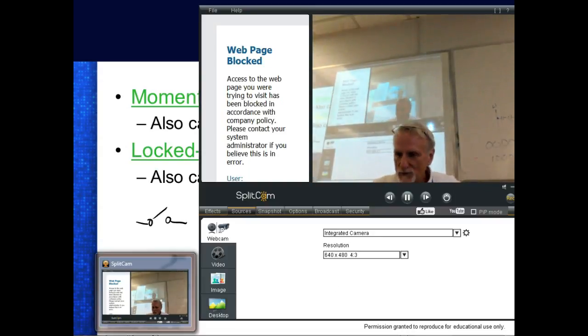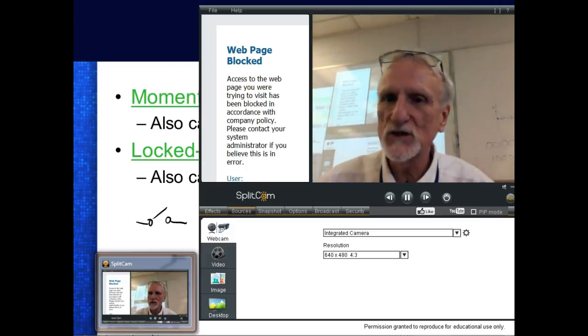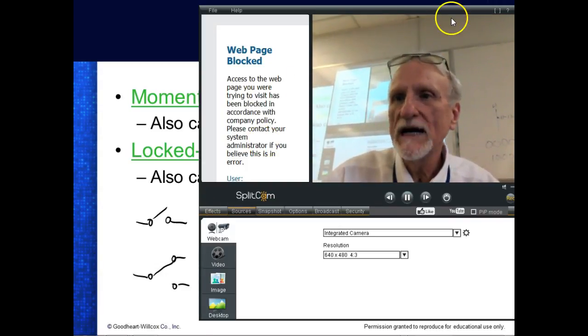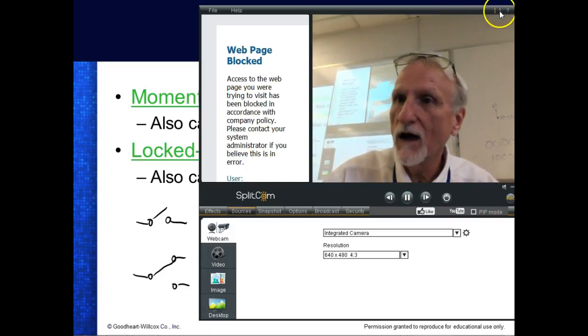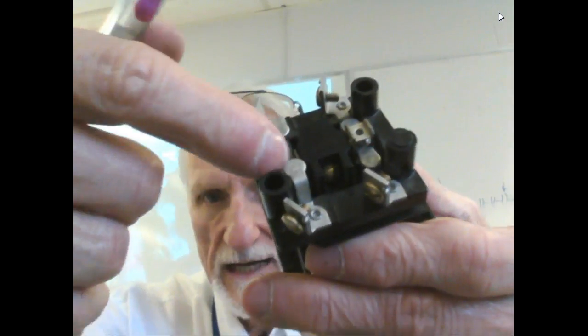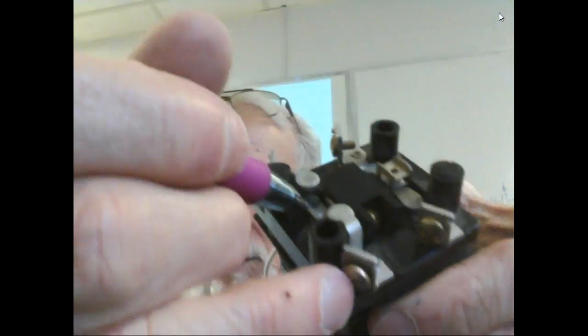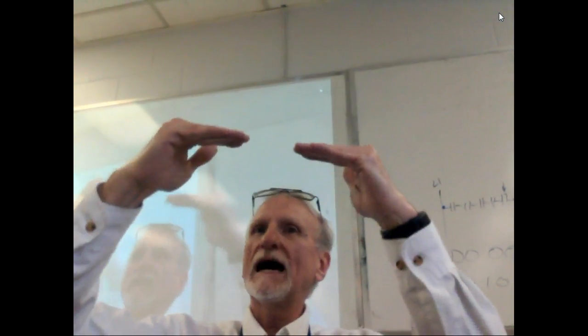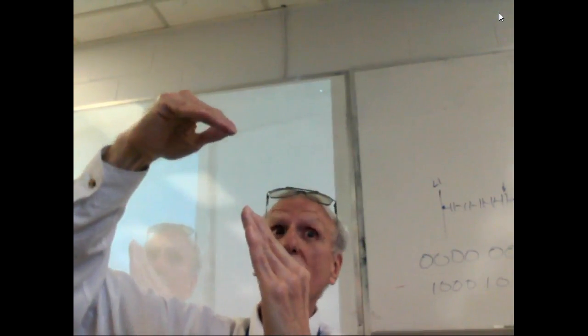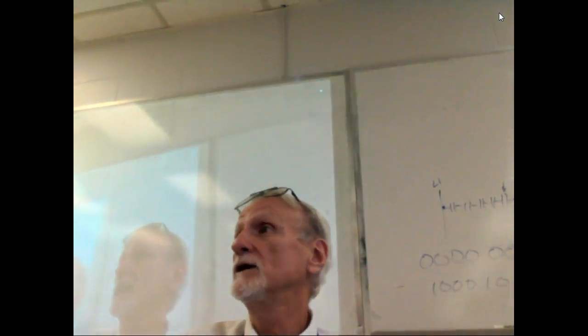So just about all our push buttons are double break push buttons. And most of our relays are double break relays. Not all of them, most of them. So I'm going to take my pin, and here's the contact right here, and I'm going to do the normally open, or the normally closed, and can you see it just floats? So what happens is that if one side gets stuck, when it breaks, this side's going to fall down, and what's it going to do? It's going to tear that other side loose.